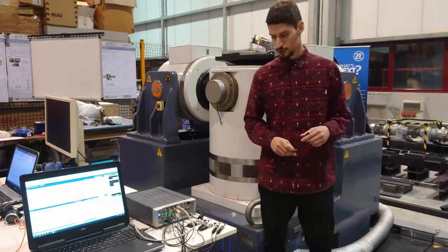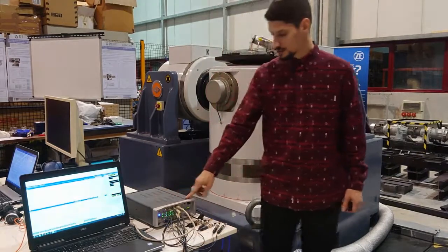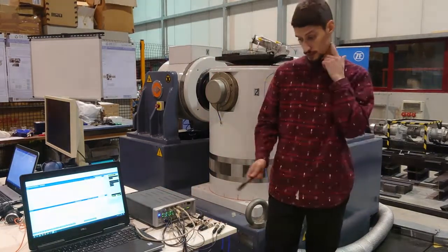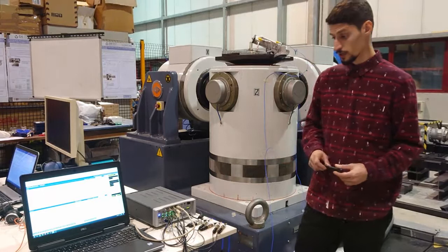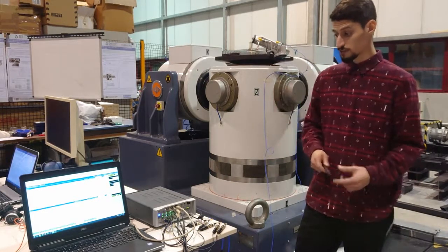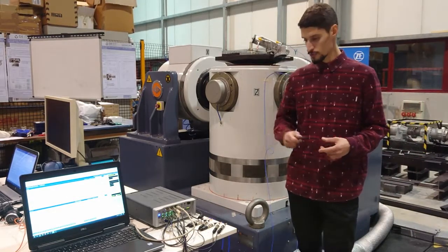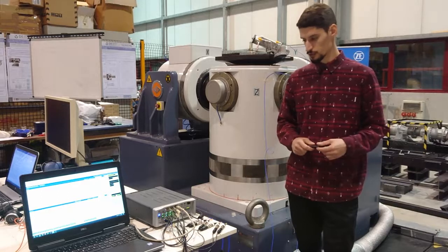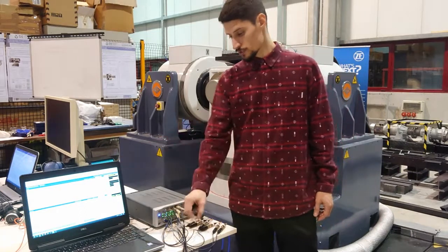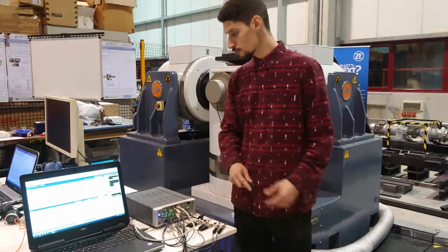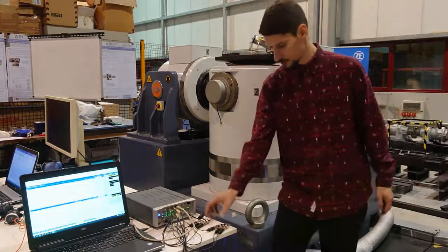The amplifiers are connected via cable into the SCADAS. This is our data acquisition hardware, the SCADAS Mobile, that is made up of the VU8 input and the DAC4 output modules. The DAC4 module is the one that allows to feedback control the shaker and therefore is critical for the vibration control testing. This SCADAS is connected with the computer through this Ethernet cable, and then we have also two three-axial accelerometers here connected into the SCADAS.